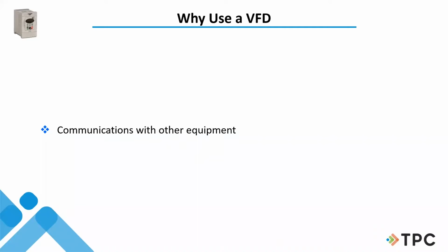So communication with all of my equipment, whether it's a PLC or all the other drives or whatever, they can all communicate and they all know what's going on. So when I get into a situation like a production line and a drive trips out, all the other drives know that drive tripped out. So we're talking very much faster than we typically would going through a PLC and then out, or just limit switches. So communications is much easier and faster.